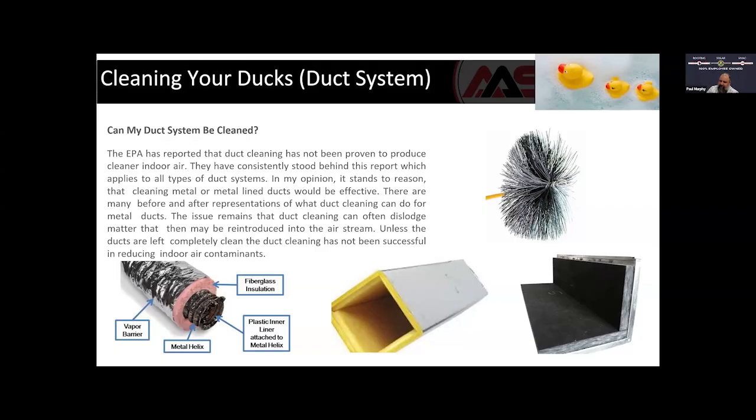We do not typically recommend duct cleaning for the ductwork that is in our spaces down here in South Florida. If you have metal-lined duct, then duct cleaning is perfectly fine. But down here in South Florida, we have three different types of typical ductwork that I show on the bottom here.